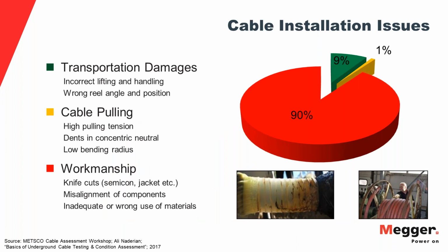So as you can see, 90%, and this is well-established statistics. There are multiple sources saying that, and even multiple utilities have published figures like that, and they only vary very slightly in percentage. Some sources might put the big red chunk of that cake at 85%, other sources maybe at 92%, whatever, but 90 is a good number to go with. So as you can see, workmanship-related issues dominate the failures of the various components of the cable.